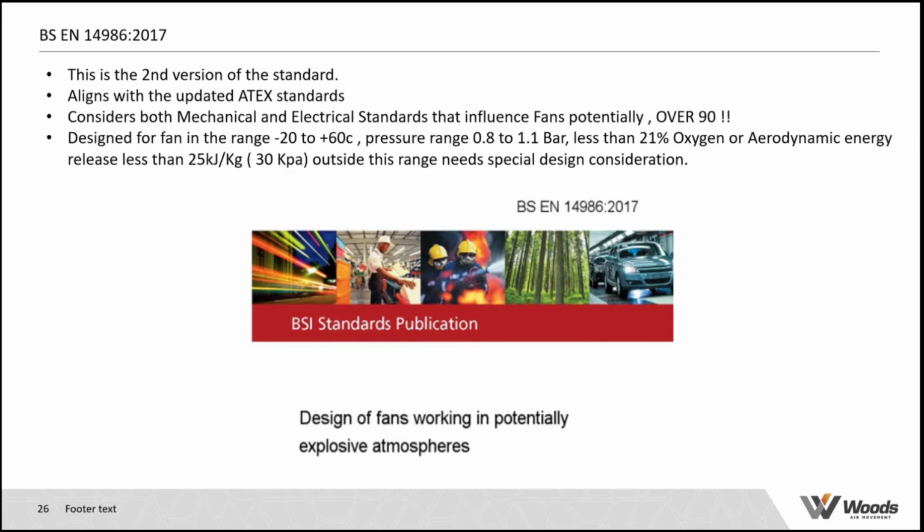It's not the only standard within the world. If we look at the US markets, there are NEMA codes and classifications, of which the basis is very, very similar to the ATEX code, but our fans cannot say they've been fully compliant with them. We comply with the ATEX code. And the other one, in more recent times, has entered in is IECEx, but they don't have a tidy fan standard. What they do, they've got electrical and mechanical standards, and so you have to become your own expert in terms of dealing with that. So we, along with the majority of the industry, will go along with the dedicated ATEX code.